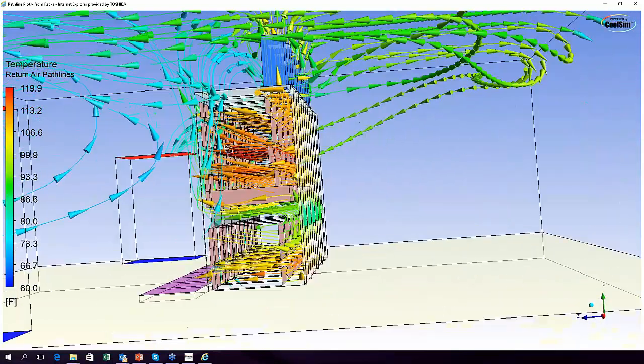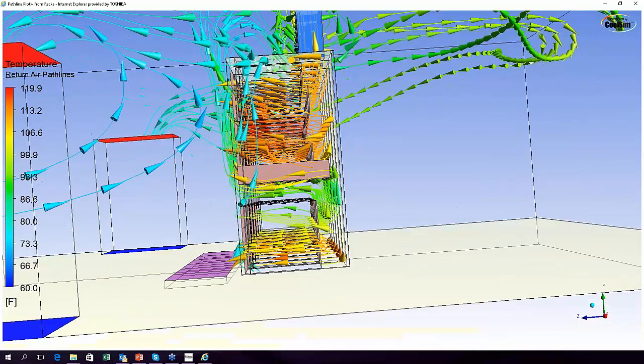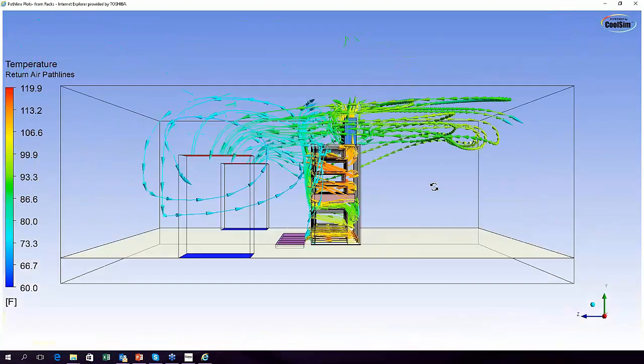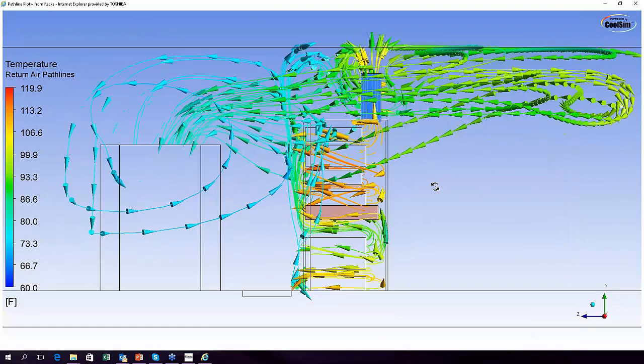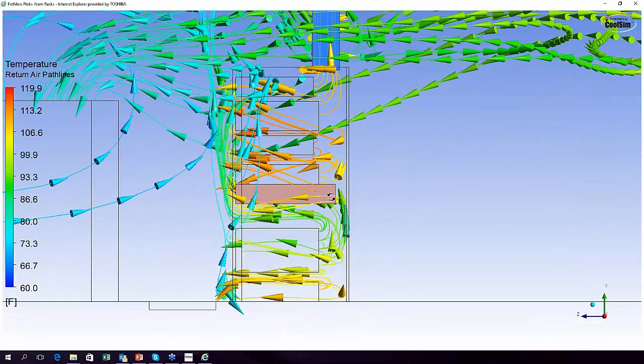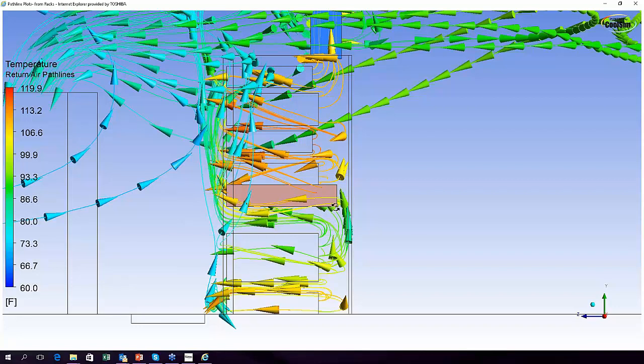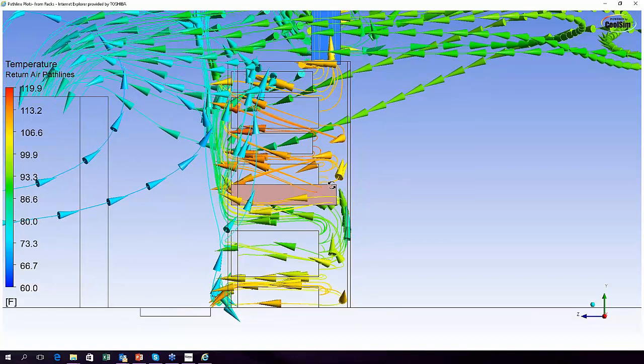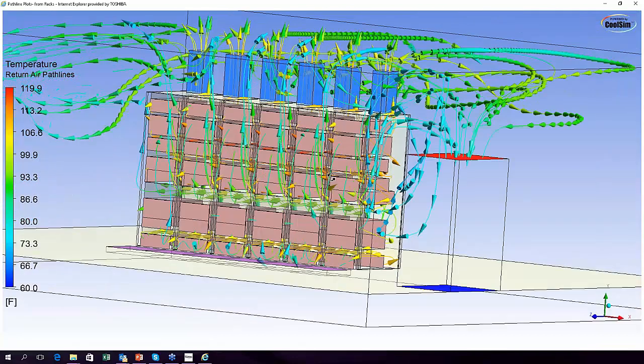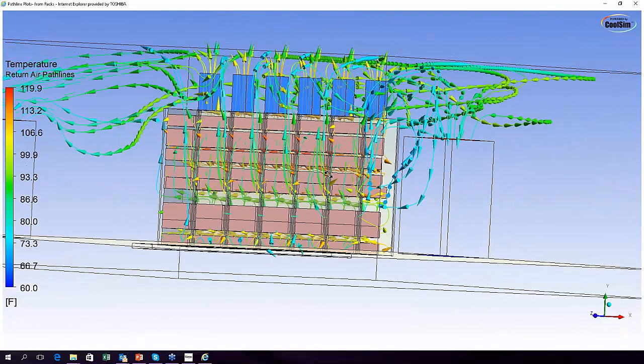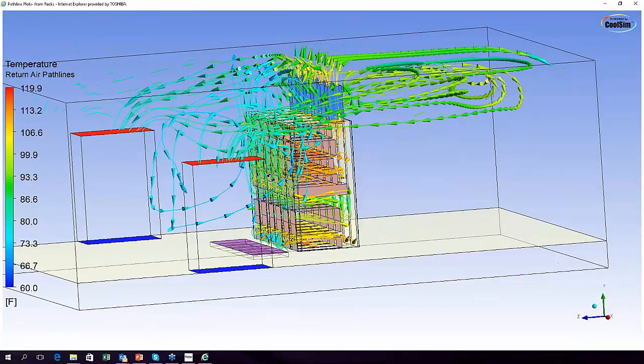So passive chimneys can be challenging, particularly if you have, let me flip this around and turn off perspective, different lengths of servers, which is not uncommon. You can run into this problem. Furthermore, if you have a high-density server sitting here that's got a big fan in it, because high-density servers do, it'll create an air curtain here, and these servers below can't get their air past this one, and that causes problems too. So I have seen this problem inside of racks, particularly passive racks with chimneys.